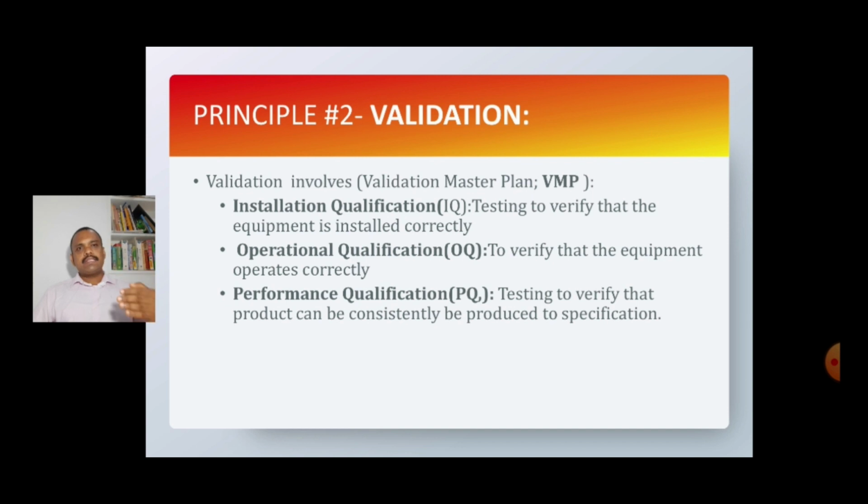The second one is the operational qualification. Now the installation is done. Each equipment will have limited values or a limit range within which to operate. For example, a temperature range: 0 to 30 is the temperature range at which that instrument can work. So you have to see whether we can operate over this range of temperature from 0 to 30. That is called operational qualification.